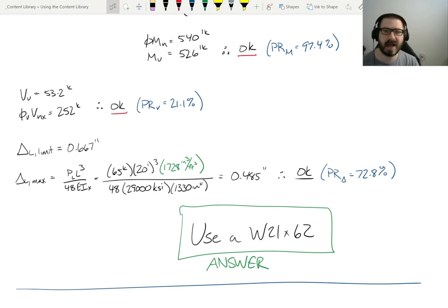It is a good thing to have in your head as you're initially sizing a plate girder, but even with girders where shear is a concern, it's something you usually address after the moment and deflection considerations have been taken care of. But I do think it's a good idea to understand that. And then on Wednesday, we're going to discuss something that we've glossed over throughout the entire discussion of columns and beams, but I think we need to address, and I like discussing it near the end, which is local buckling. I'll save that for our discussion on Wednesday.